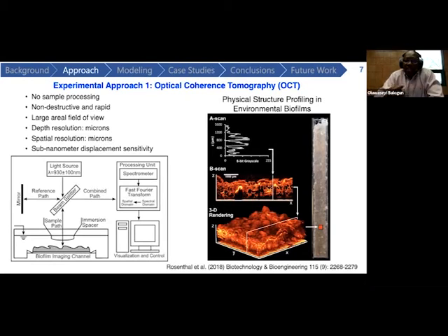So the index of refraction, you will see later, is directly correlated with the morphology of that partially transparent material. Some of the interesting attributes of this measurement technique are that it's non-destructive, it's rapid, and it requires no mechanical contact with the material. The resolutions are on the micron scale, both in the lateral as well as the depth, the axial directions.